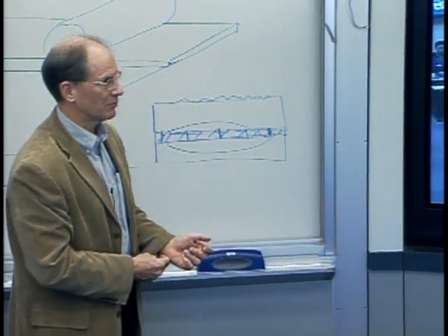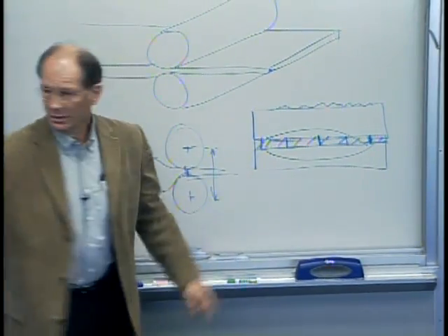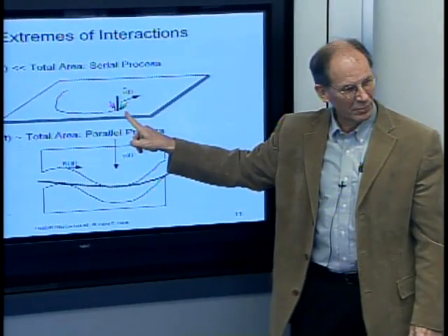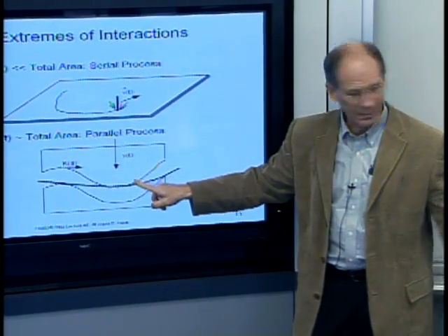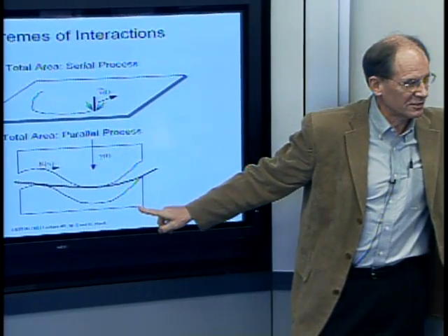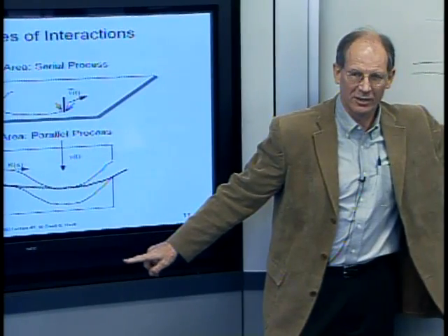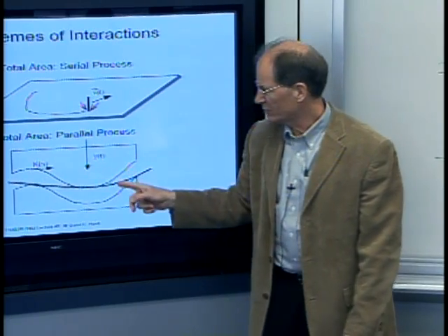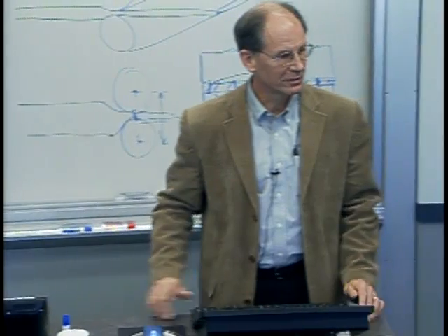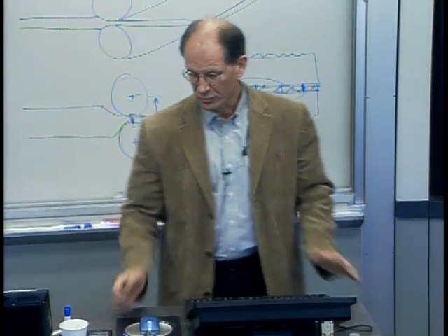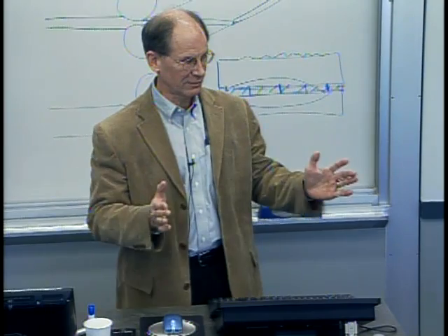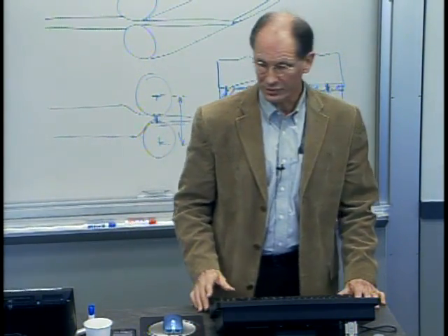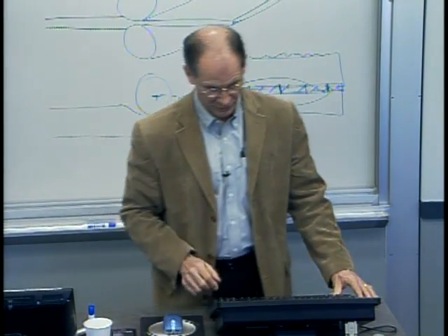What can I actually change on a process? What can I change in real time, millisecond? What can I change maybe, in this case, this is an unusual example, on a frequent basis? But in most cases, the major change you do with tooling and things like this is on an hourly, shift, yearly basis. So your ability to affect the output once you've kind of literally cast it in stone is greatly changed by whether it's a parallel or a serial process.